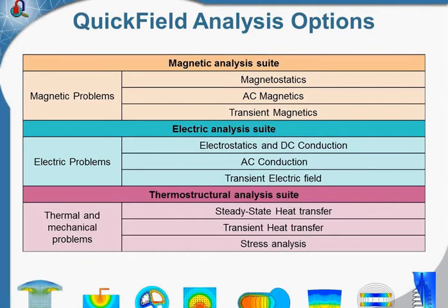Thermal analysis may be helpful to estimate the capacitor stability at given operating conditions or maximum loads permitted. Magnetic analysis helps to evaluate the capacitor's inductance, and mechanical models may also be needed to estimate the mechanical stability of the capacitor as an assembly, or at least to understand whether detailed mechanical analysis is required or we are in the safe zone and there is no need for more complicated mechanical analysis.